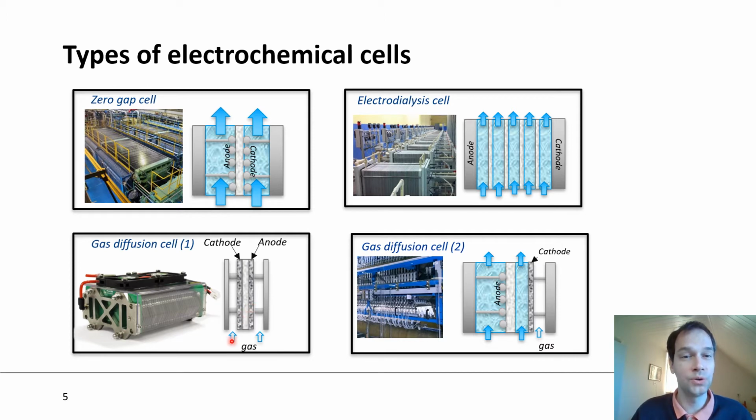It's important to note that even though it seems that this cell is dry, it's not. You always need to humidify the gases to make sure there's enough water in the electrochemical cell present, because basically electrochemical cells need water to function properly.